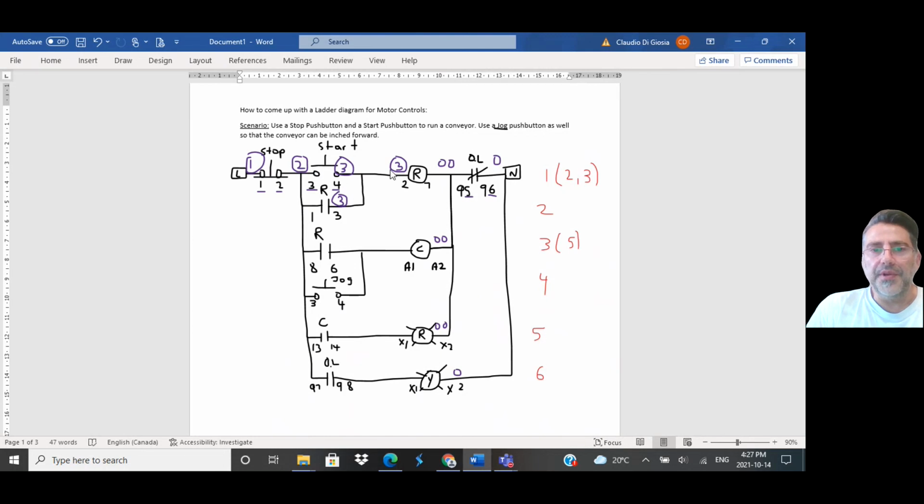So I stopped at number 3. I'm going to go down. Since there's no component here, these are all daisy chained, so all of these are number 2. That's a number 2. This is a number 2. This is a number 2. And we've got 2 more, one there and one there. All these would be labeled number 2 in your control panel.